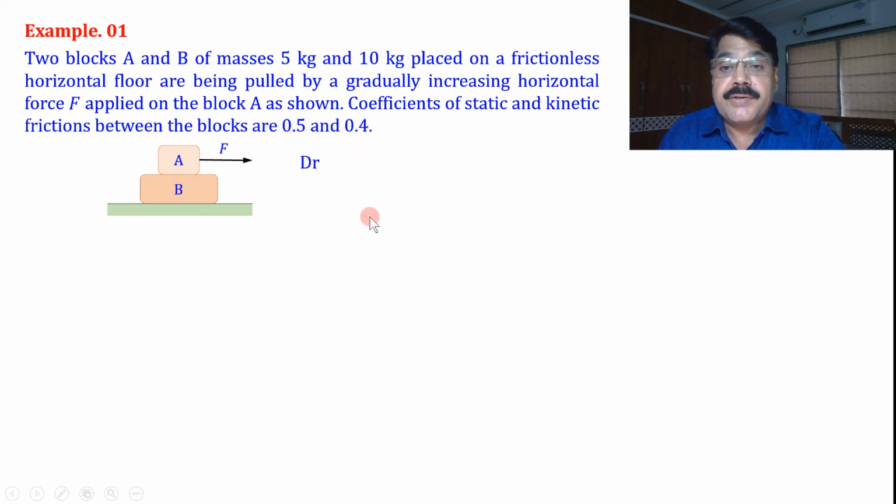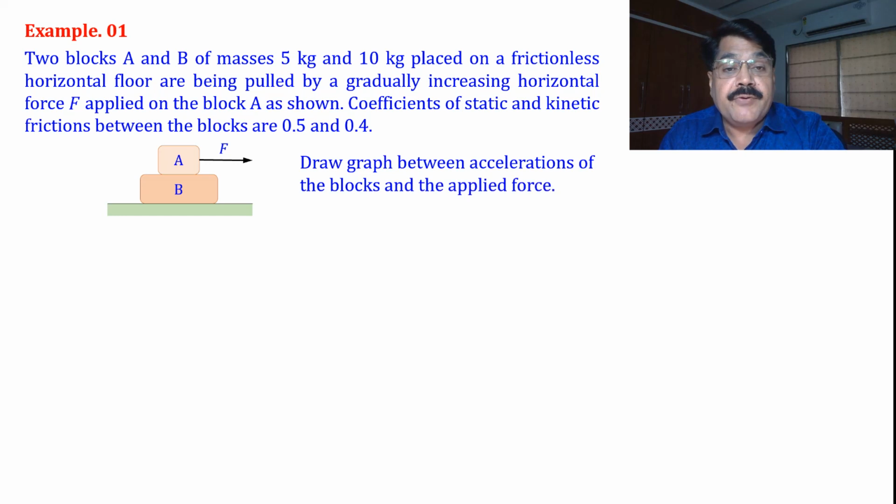And what we have to calculate? Draw a graph between the accelerations of the blocks and the applied force F. It means we have to explore the accelerations of the blocks for the range of force F from 0 to a sufficiently large value when there will be sliding between the blocks. Now, how do we think about the solution?